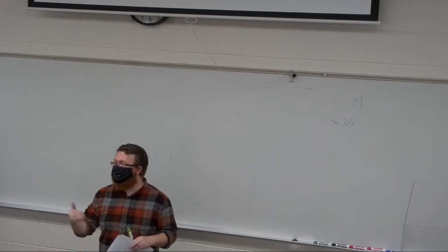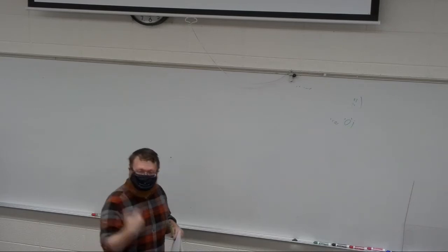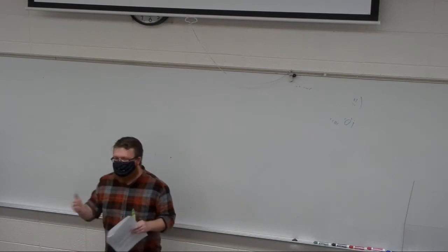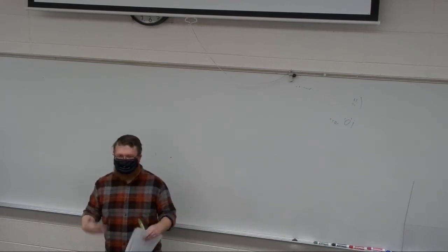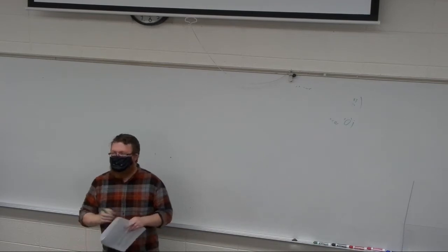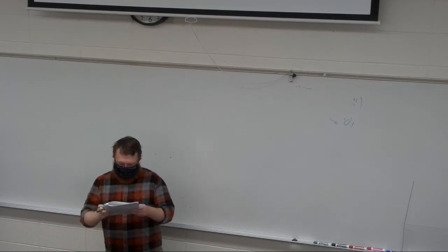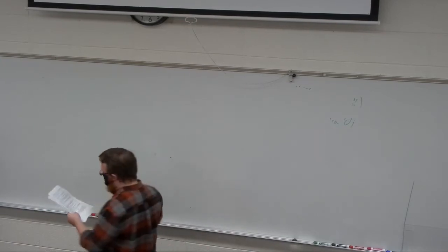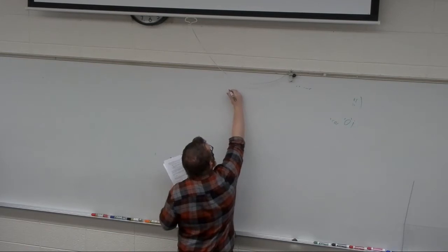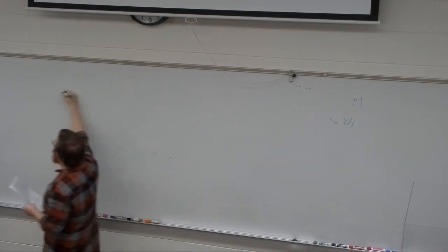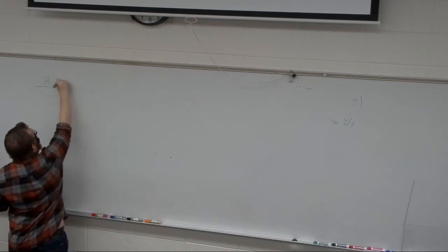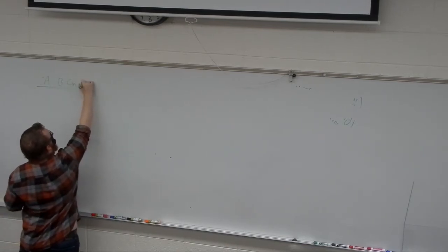So if a carry comes in, will it carry on through? So those are the 2 ideas, generate and propagate. And we can calculate this just using essentially XOR gates and OR gates really quickly. So it helps us to recognize that we can define, let me draw up an adder table here so that we can keep this in mind.